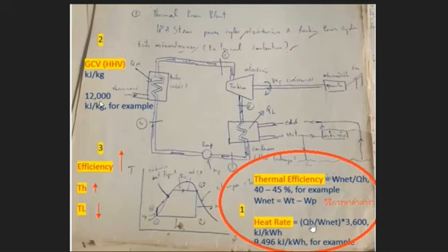The heat rate is a very important value that we need to calculate, because the heat rate will determine how much coal we need to provide in order to supply enough heat to the water to get the certain amount of power that we need.